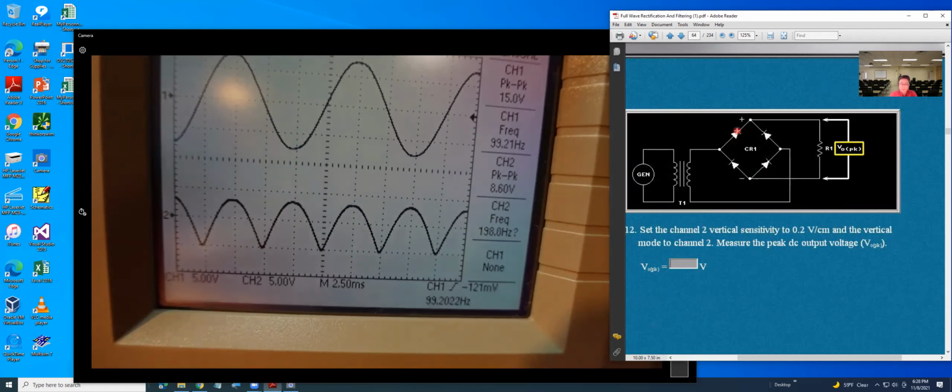So that one will be on and that one will be on. So R1 gets a 0.6 to 0.7 volt drop when they are on. If you get 0.6 volt here and 0.6 volt here, that's telling you the DC output will be how many volts?